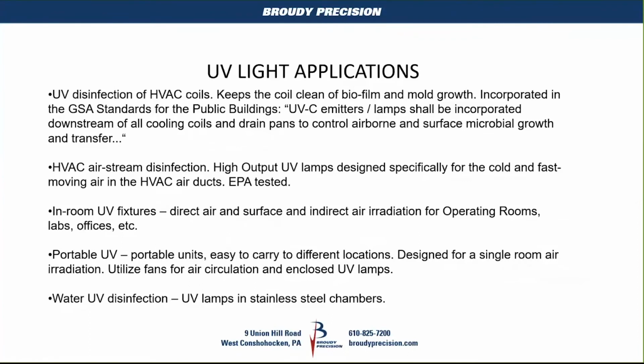Talked about this a little bit already. So, UV disinfection of HVAC coils. Now we're going to keep the coils clean of biofilm and mold growth. And there's the GSA standard for public buildings that's now talking about UVC emitters and lamps shall be incorporated downstream of all cooling coils and drain pans to control airborne and surface microbial growth and transfer. So we may see this in the very near future, especially with what's going on in our country. It'll be a matter of compliance.